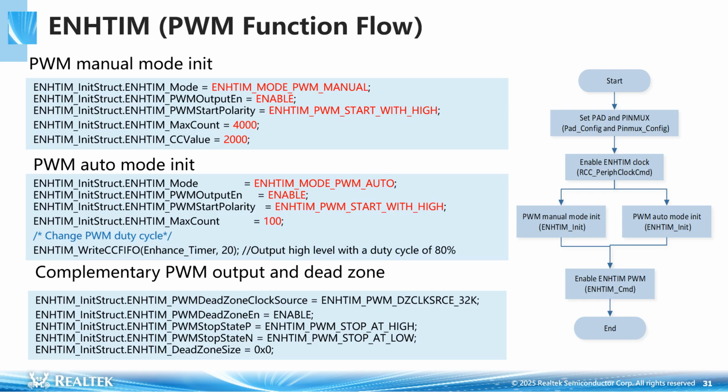Auto mode initialization process. Step 1. Set the count value for 1 period in the initialization structure. Step 2. Use the enhanced timer write CC FIFO function to set specific PWM waveform output. You can enable PWM complementary function to output PWM-P and PWM-N waveforms.